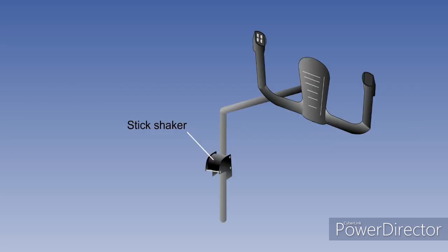The stick shaker is intended to represent the aircraft's natural buffet by replacing it with a tactile warning. The noisemaker is added in parallel to ensure that the warning is noticed if the pilot's hands are not on the controls, for example, if the autopilot is engaged. The device consists of a pair of electric motors, one on each control column and rotating an eccentric weight to generate vibration.